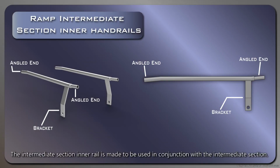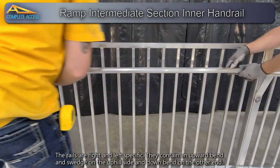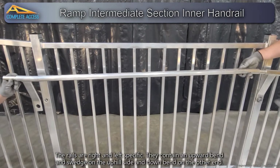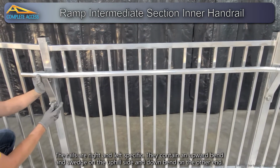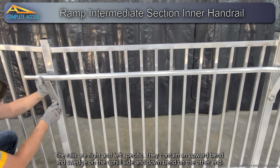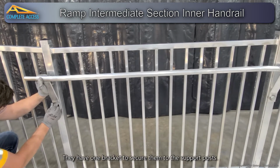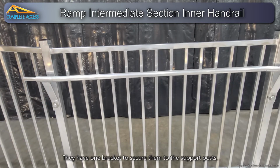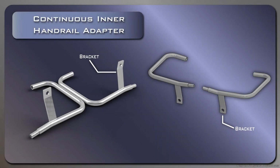The intermediate platform inner rail is made to be used in conjunction with the intermediate platform. Just like other inner rails, these inner rails are left and right specific. They contain an upward bend and a swedge on the uphill side and a downward bend on the other side. They have 1 bracket to secure them to the top of the leg through the picket guard.